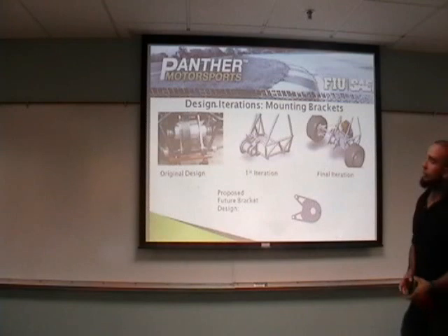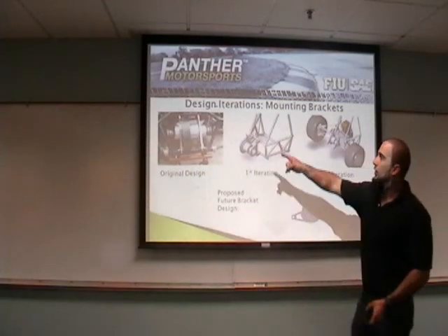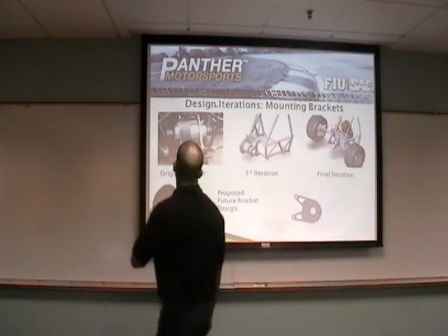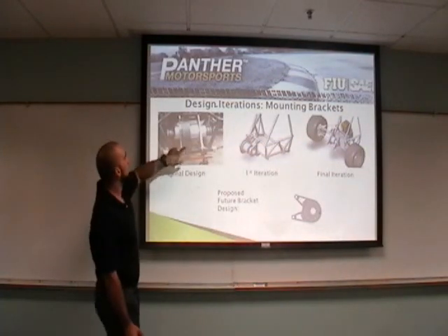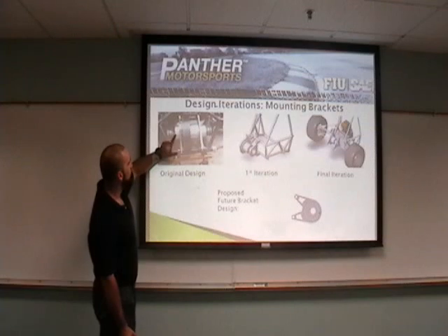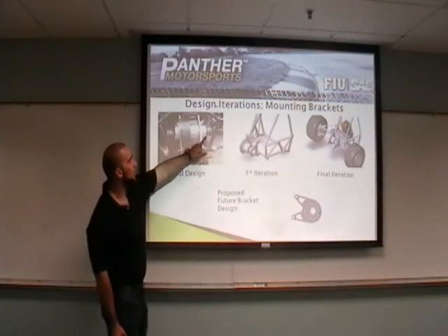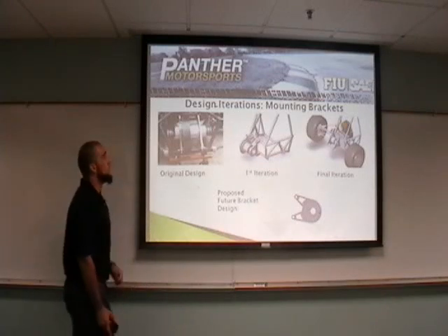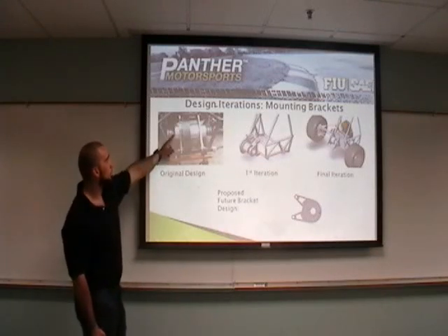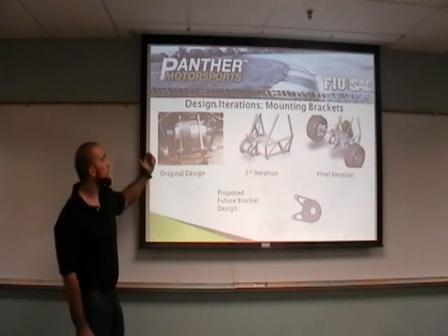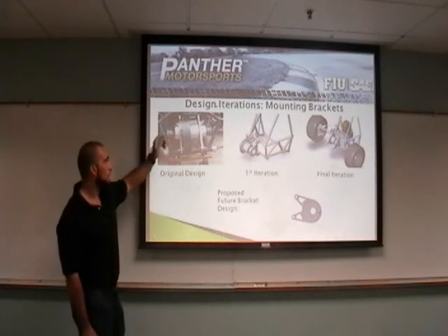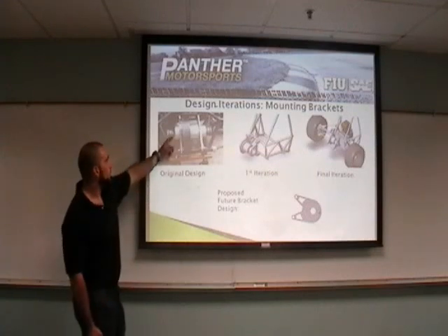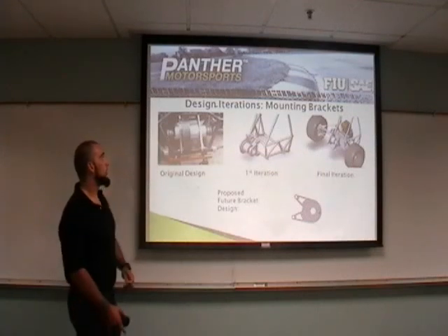So for the 2014 season, as you can see here, it was an inboard differential. One of the main issues for this design was, number one, some alignment issues. Number two, lack of adjustability due to the triangulation of the chassis. And number three, the mounts here caused leaking. One of the last updates to this differential was seals to be placed in here,